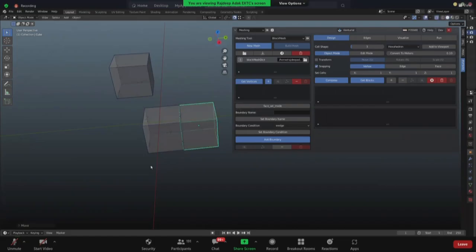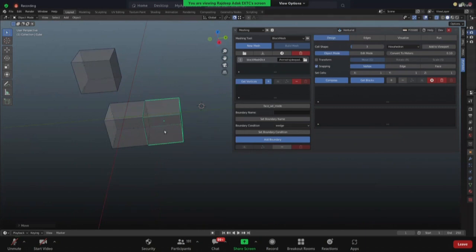So I'm going to snap it to this block right in the middle. Then I want to create something like an outlet flow. So what I'm going to do is I'm just going to hold this and extend it a bit onto the y-axis. So in order for me to do that, select this block, press the S button. And then press the Y button.